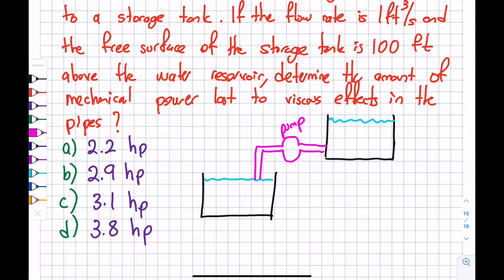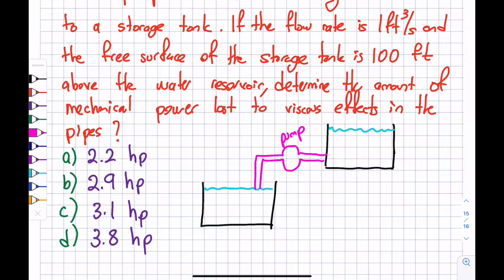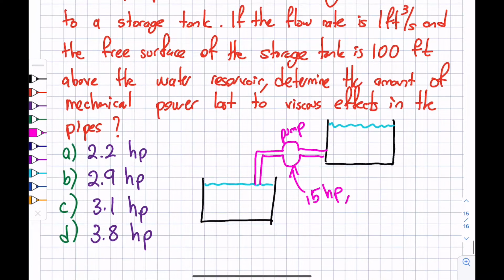It's pumping the fluid from this container, it says reservoir, to the storage tank. Okay, and it says that this particular pump has 15 horsepower, that's the power of it, and is 90% efficient. I want to talk for 1 second about, is this an unrealistic number, 90%? Well, if the pump power is over 10 horsepower, it can go up to 93% or 95%. So this is fairly realistic, okay? So this exists in real life. All right, that was a side item.